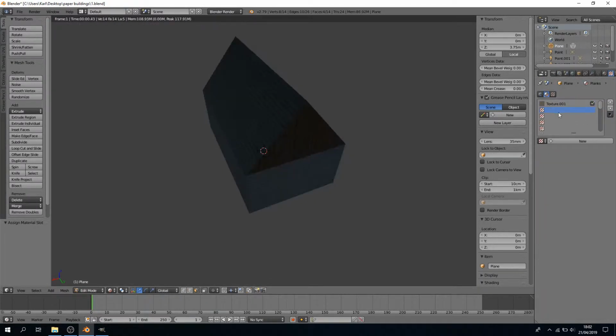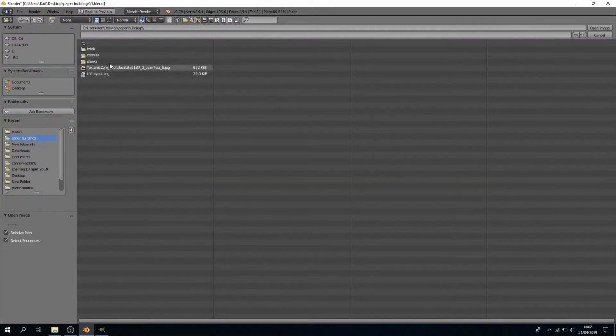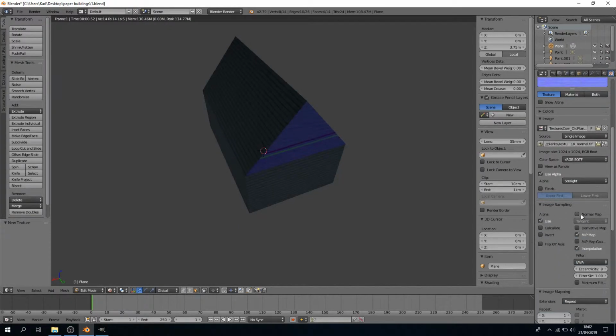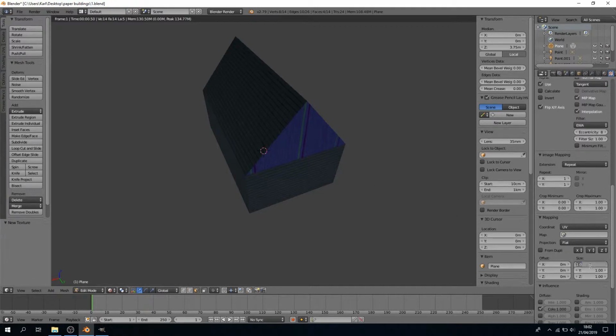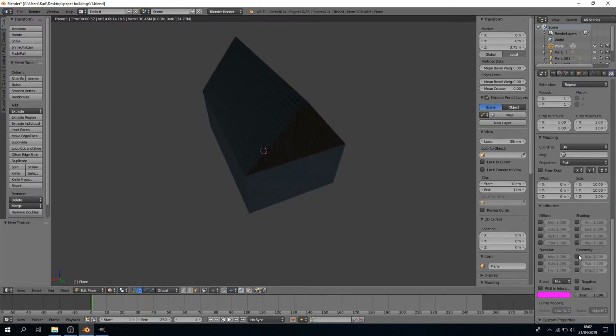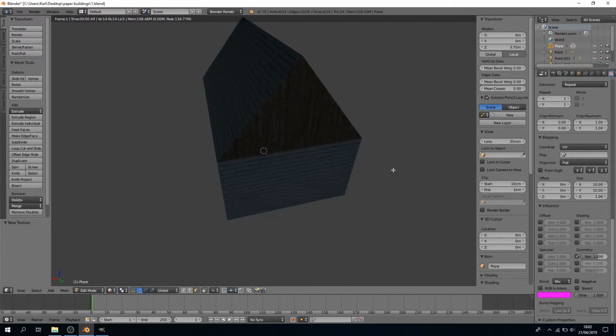And since the texture comes with a normal map, I'm also going to edit it. It gives a little extra detail to it. I just need to tick normal map, flip XY axis, so it's going to go along the same direction as the color map, and apply the same size. Finally, I'm going to say that this does not affect the color, but it does affect the normal geometry. Okay.